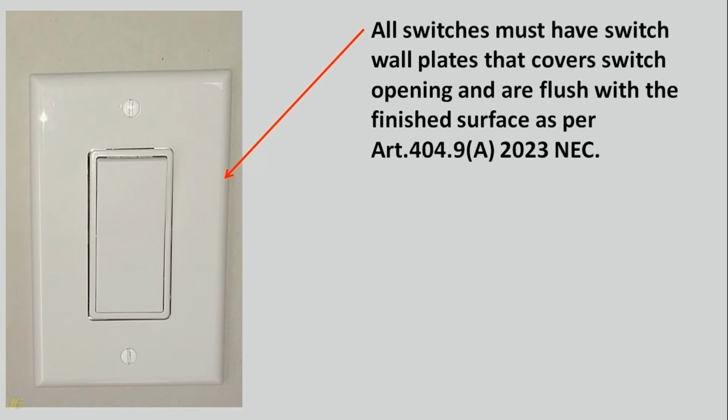All switches must have switch wall plates that cover the switch opening and are flush with the finished surface as per Article 404.9, a. 2023 NEC.